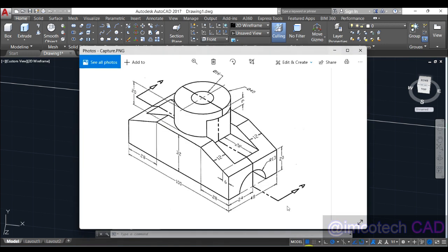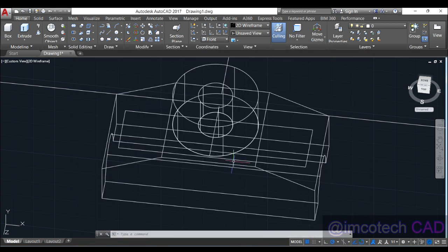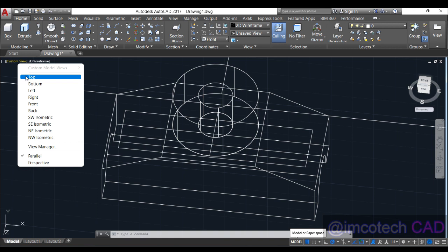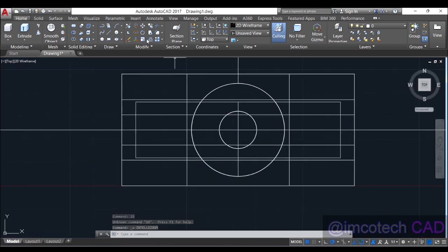But I want you to see something on the diagram. You can see that it gave us the internal distance 28 units, which means it's also 28 units inside. So I'm going to offset this line here by 28 to make it cross the rectangular shape, leaving the remaining part of the cylinders out. So from the top view, we are going to offset by 28 from this place inside, also from this place inside.